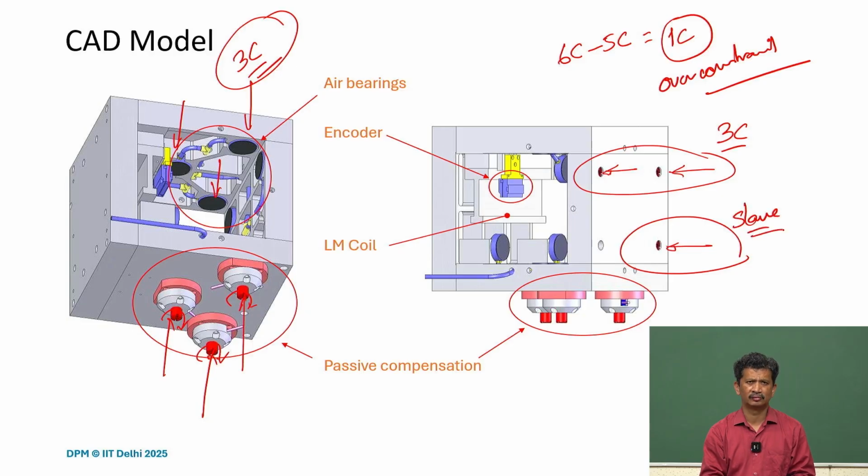Slowly fine tune so that it doesn't create any problem. But with the air bearings, what you realize, moment you tighten it a little bit, it over constrains, and then you start having vibrations, pneumatic hammers, all those kind of problems. So I think those are some lessons you learn when you really start working on those systems.